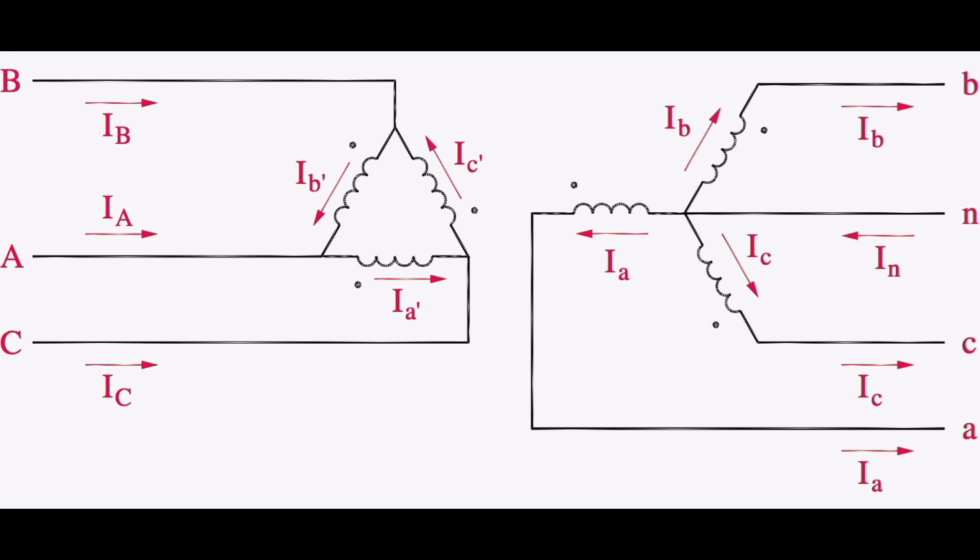On the other hand, the Y configuration has some advantages, such as it provides better voltage regulation due to the neutral connection, which allows for easier balancing of loads between phases. This results in more stable voltage levels. It also gives better insulation coordination, especially for higher voltage systems, as the neutral point provides a reference for the ground and helps in managing transient overvoltages.